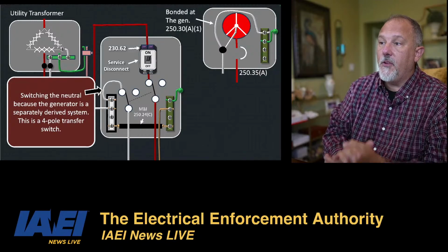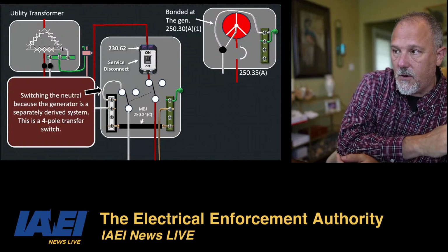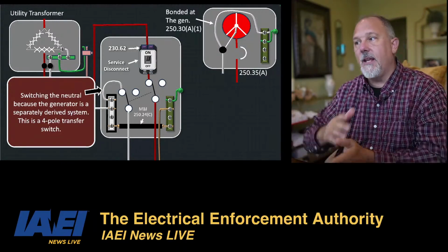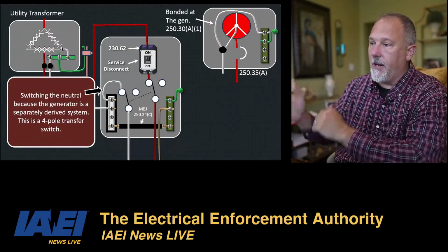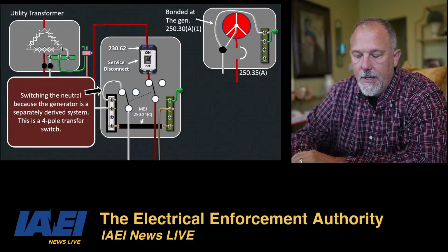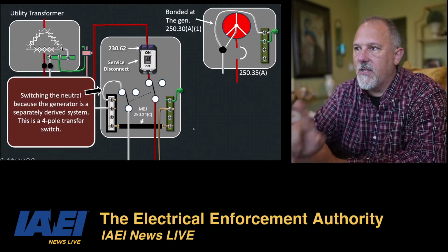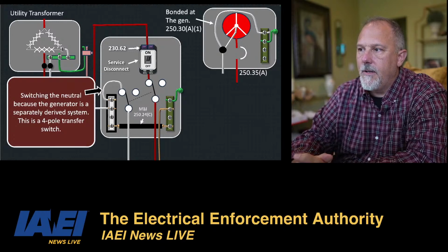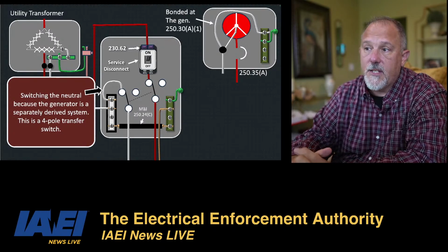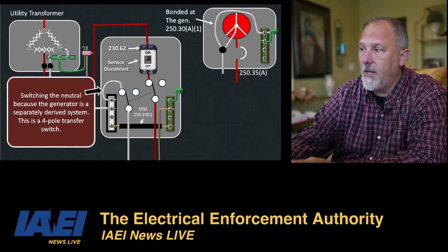So that when I'm on the utility, I'm connecting that neutral to the utility transformer. But when I'm not on the utility, I'm going to feed it from the generator. And we're going to walk through this to help you get this, all right? So that's your reference there. That's standard service equipment. So go to Article 230 and it'll show you need to bond those 2 together.